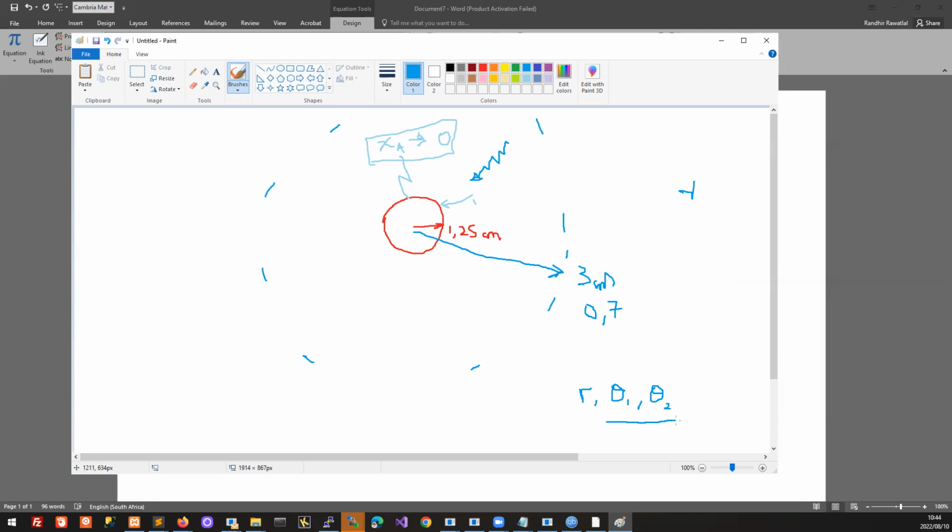And we are not told anything that leads us to believe there are gradients in the angular direction. So if we think about diffusion with respect to the angles, whether it's on the plane like this, or I'm not sure if I can draw it well, but in the angle coming out of the page also, we are not told that there's anything special going on in terms of the angles around the particle. So if we assume that all the changes are happening in the radial direction only, then we can neglect these